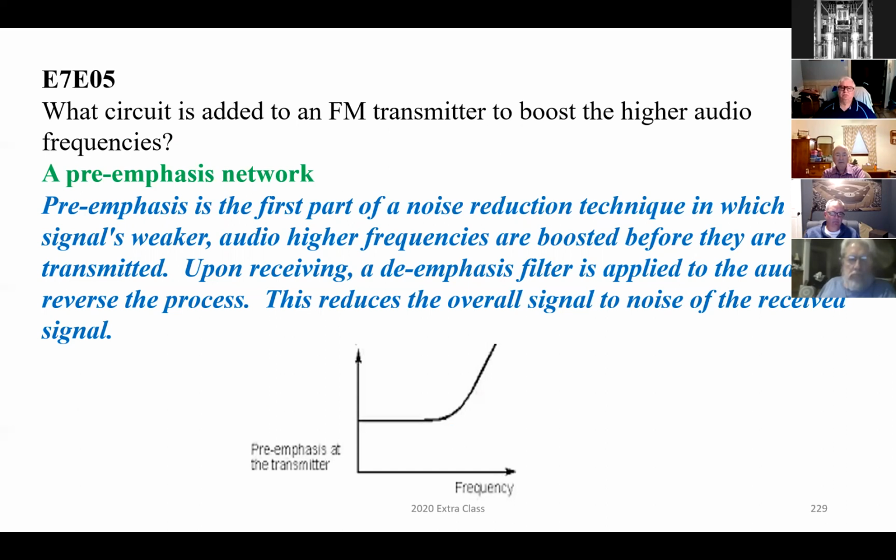Yeah, and this is very much, if you remember cassette tapes, a very similar process to what was used for noise reduction there with like Dolby B and Dolby C, and really probably more accurate would be DBX, which would go ahead and compress that signal down, and it would be recorded on there, and then it would be decompressed during playback, and it retains much better sound quality afterwards by using that than if it had just been recorded straight and played back.